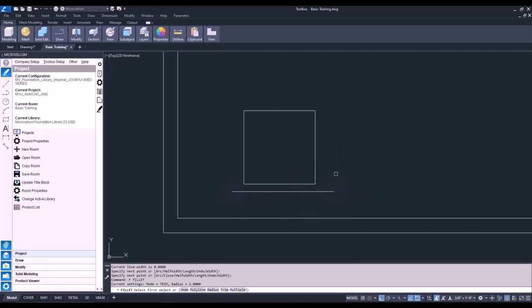Remember to type R before selecting any objects and enter the new radius amount. And this amount is going to be 5. So enter that and hit enter, and now select the objects. Now we need to make the face and draw a jagged polyline for the actual bottom. So next is the circle command. We're going to type C and enter.